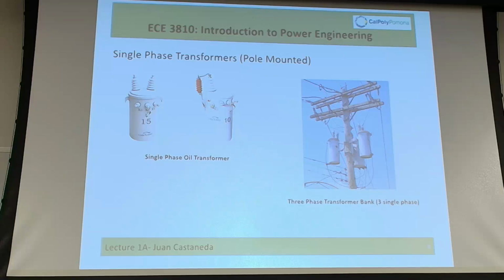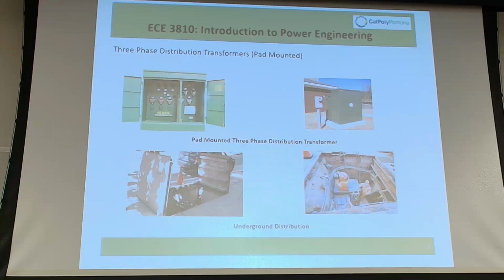But for the most part, in residential areas, you will see one like this, this one is fan mounted. You can feed on average 5-6 customers per transformer, more or less. But as I said, there's not much to it. There's a core, there's a winding, insulators, and oil, and that's it.